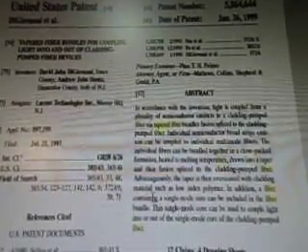Individual semiconductor broad stripe emitters can be coupled to individual multimode fibers. The individual fibers can be bundled together in a close pack formation, heated to melting temperature, drawn into a taper, and then fusion spliced to the cladding pumped fiber. Advantageously, the taper is then overcoated with cladding material such as low index